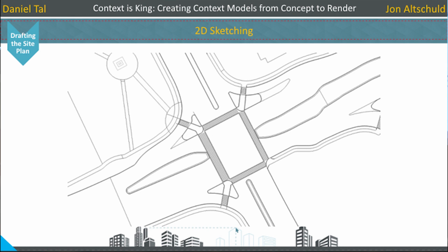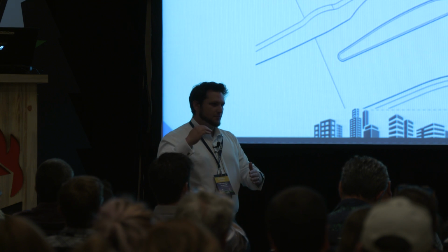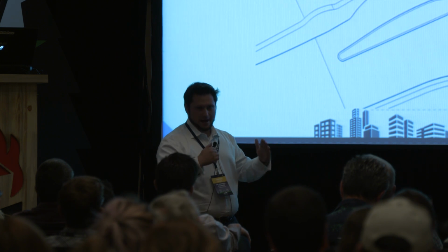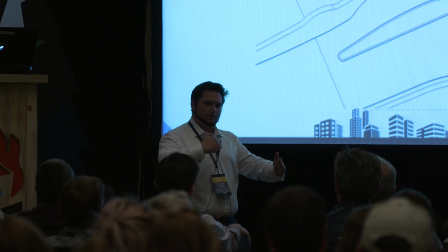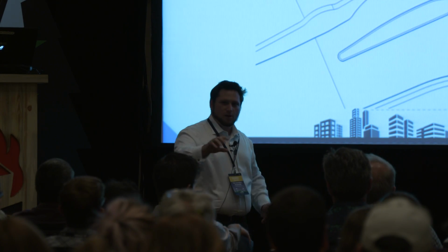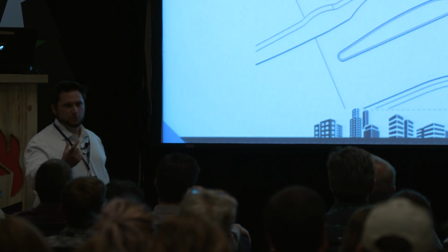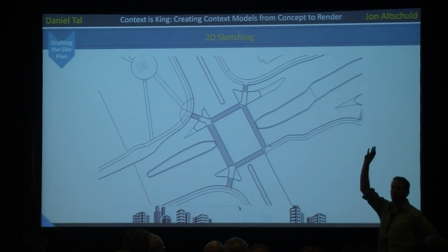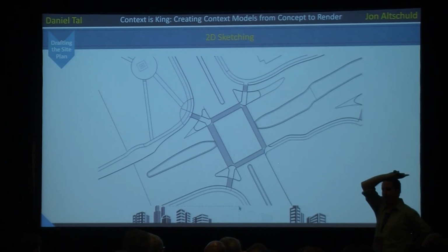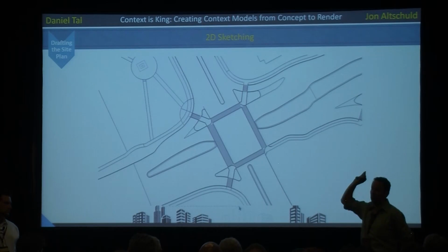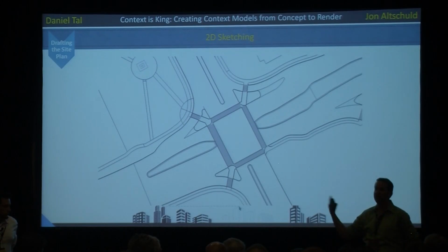Again, let the extensions help you. So one thing to think about, curb and gutter, if you use a profile builder or follow me, even if it's a very simple profile of the curb and gutter without curves, you can use that. And if you do that, then you don't have to draw the front of curb, the bottom of curb, and the top of curb. You just have to have one, offset it 1.5 feet for the entire thing. So you have your street, you have your planter bed or sidewalk, and then your profile builder, when you go to 3D, or your follow me, will fill in that curb and gutter gap. Who's used Profile Builder? There's Profile Builder Pro. It's on the extension warehouse. It's a great tool in terms of the automation. If we have time again, we'll demonstrate Profile Builder for you.